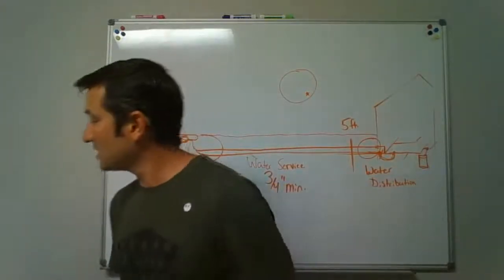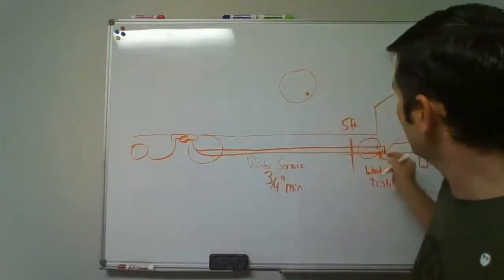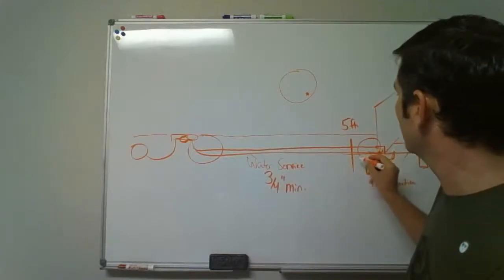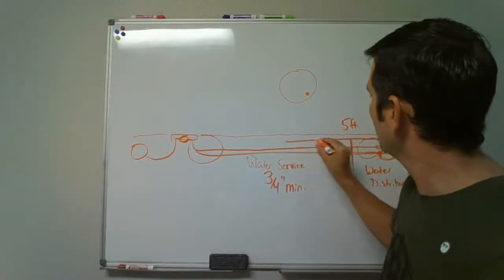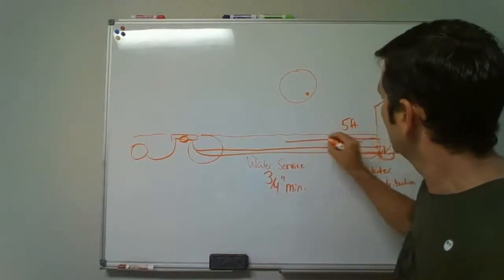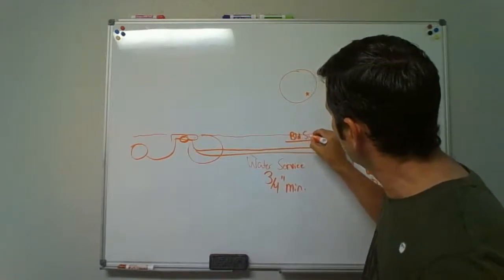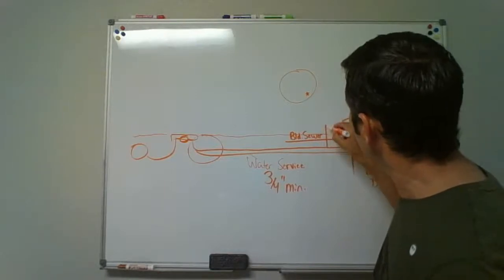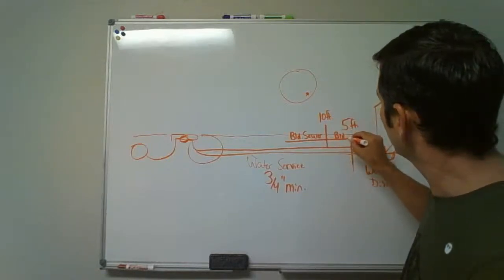Now it talks about this next one, 603.2. It says separating this line, not only do you have a water line coming in, but you're going to have a sewer line going out. Okay, let's just say we got a sewer line coming out. This is called building sewer. And then at 10 foot outside the building wall, it goes from building sewer to building drain.